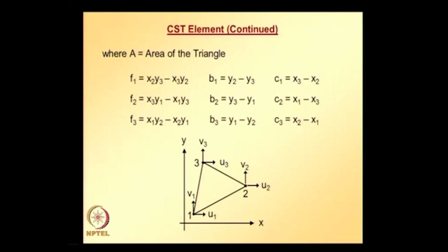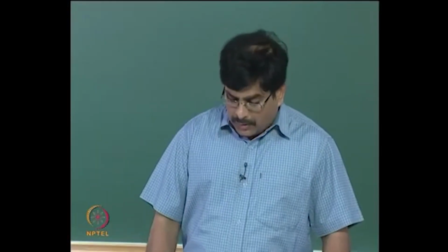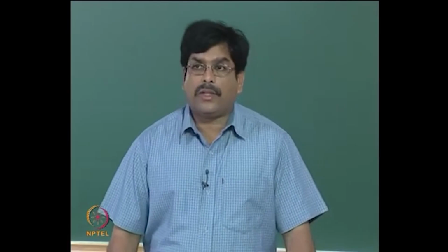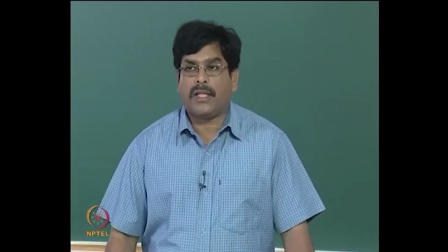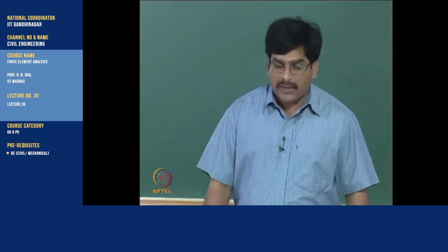And this is how we can express displacement in x direction and y direction in terms of finite element shape functions for that particular element and the nodal values. And these two trial solutions, that is displacement in the x direction and displacement in the y direction, can be written together in one equation.